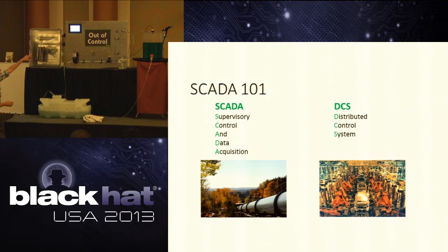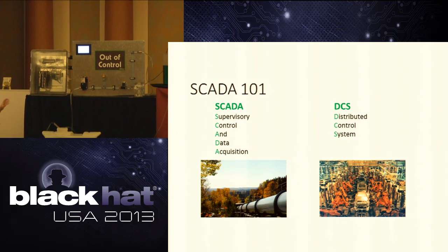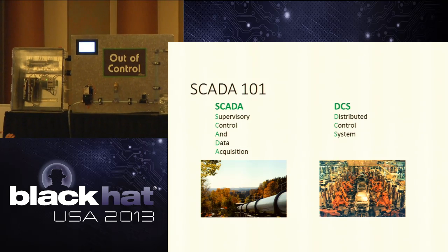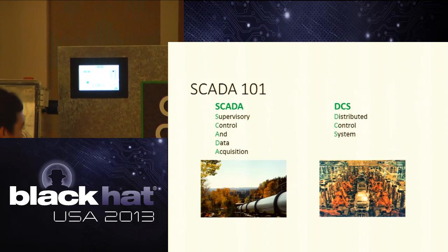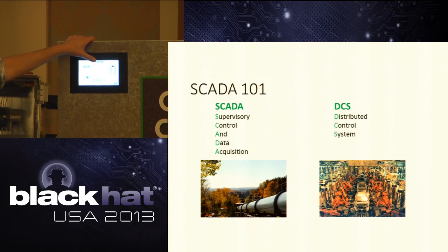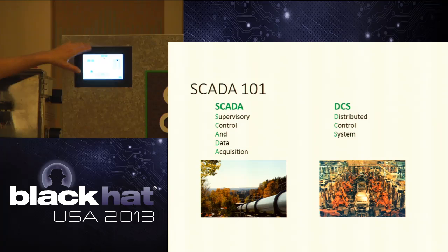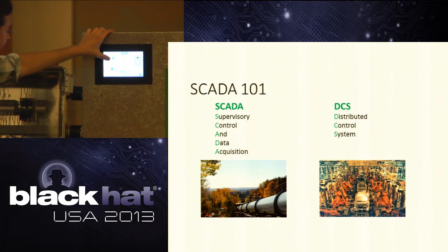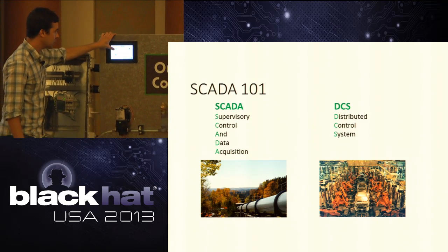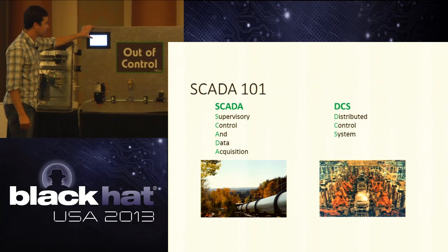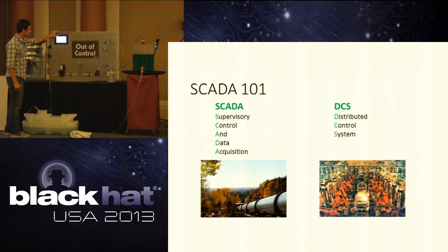One other thing that we have up top is this little screen right here. That screen is called an HMI, and that's kind of the visualization of the process. And we can give you a quick show of what it looks like to actually work. All this stuff is touchscreen, and you usually see these installed in the field. The HMI is the operator's view into the process, and it also allows some control. And you typically see alarms pop up if you have any conditions that are met on the HMI.